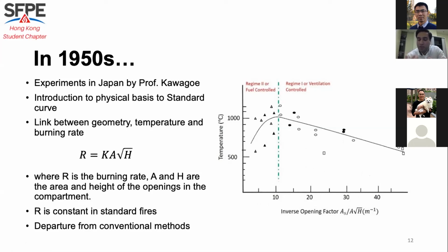Until the fuel is completely burned up, the fire will stay. So there was no deficiency of air for combustion. But in this case, when you are dealing with a ventilation controlled fire, the fire will stay only as long as sufficient air is present. So maybe fuel is present, but there is not enough air. That's why it is called ventilation controlled fire scenarios.